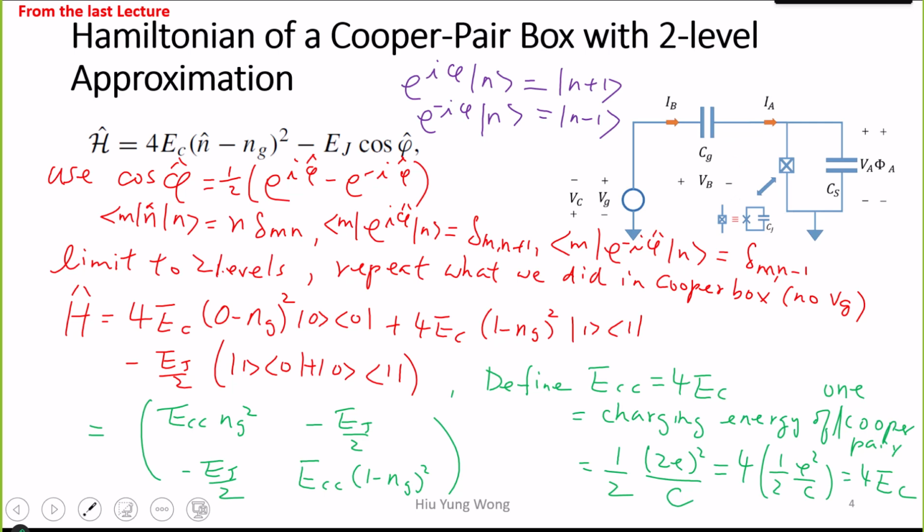We went through the math to come up with the Hamiltonian, and then we promoted the variables to operators. Do you remember what the conjugate variables are? Sometimes I call them generalized momentum and coordinate for this system, or for an electrical circuit. What were they that we used earlier? Charge, yes, charge is the generalized momentum. And how about the coordinate? Flux, yes.